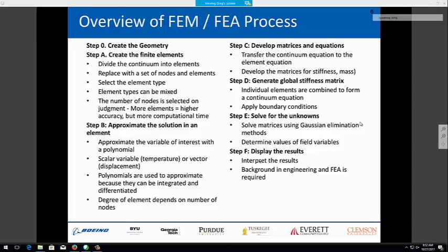Okay. So when I start to run this spar analysis, this ANSYS Workbench, or ANSYS in general, does have a geometric modeler, but it's quite terrible, so I don't advise that you use this. But the first thing I need to do is start with engineering data. Okay, so within engineering data, you guys can see this pulls up a bunch of data sources. This is essentially all of my material properties.